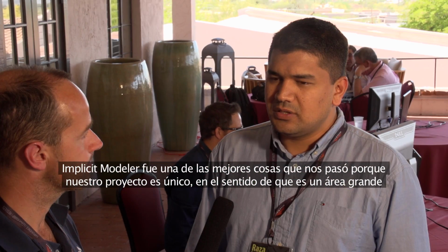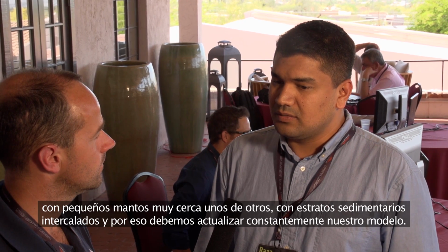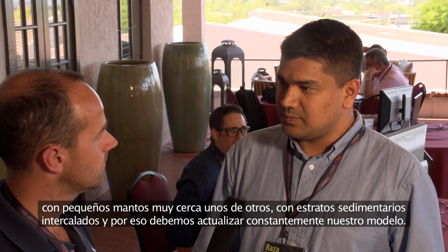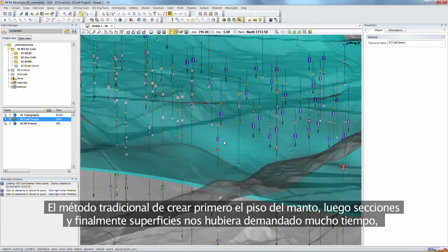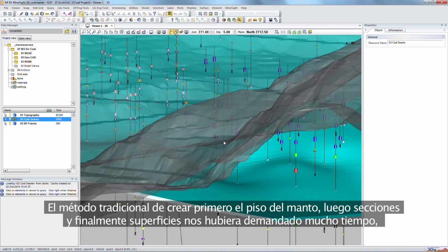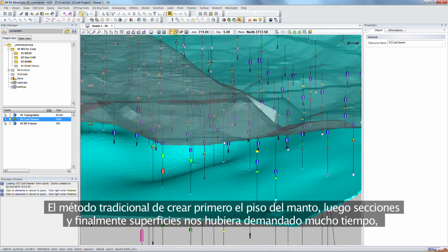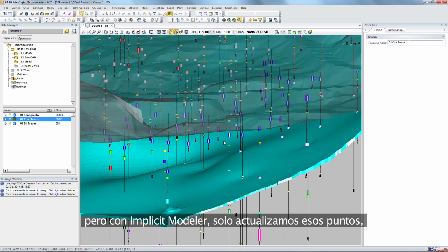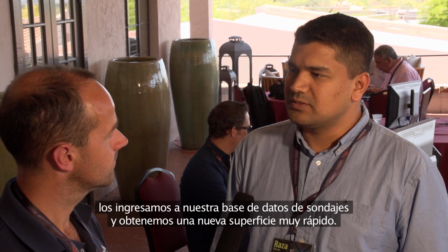Implicit modeler was actually one of the best things that ever happened to us, because our project is unique in the sense that it's a big area with small seams which are kind of close together and have partings in them. So for us, we are constantly updating our model, and the traditional way of doing footwalls and then doing sections and then creating surfaces would have taken so long. So with the implicit modeler, we just update those points and get in our drill hole database and get a new surface very quickly.